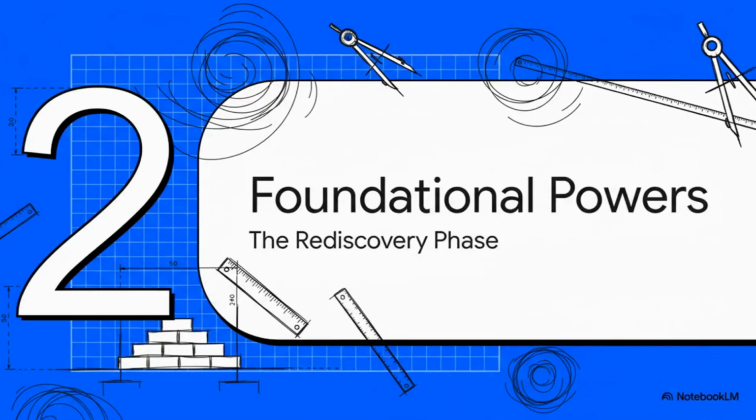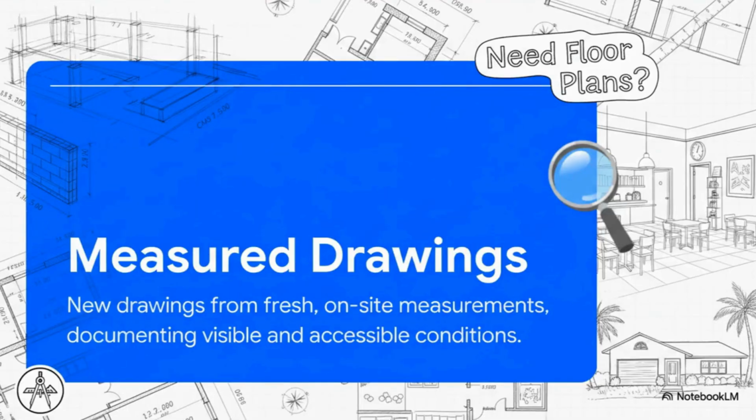So how do you kick off this quest? Well, you start by rediscovering the building's dimensions using what we're going to call foundational powers. These are the time-honored, tried-and-true methods that really are the bedrock of this whole entire process. And here it is. This is the key term you need to know. Measured drawings. This isn't a guess. It's not based on somebody's memory. It is a brand new set of architectural drawings based on a fresh, physical survey of the building, documenting everything you can see and everything you can get to. This is the professional standard, period.